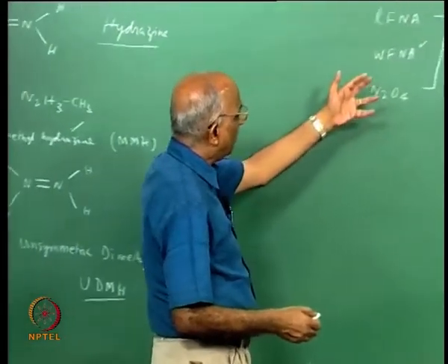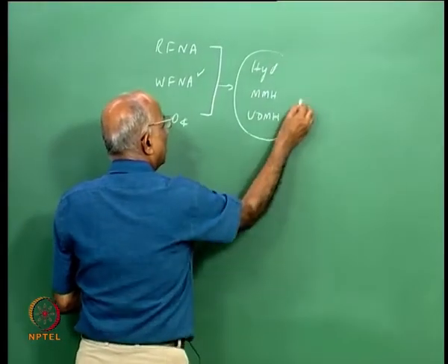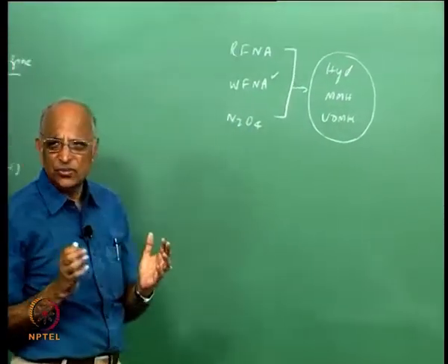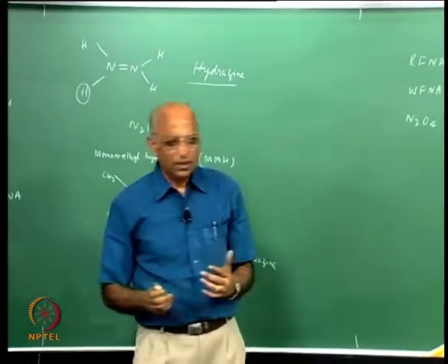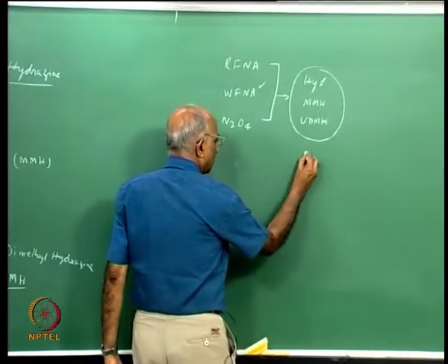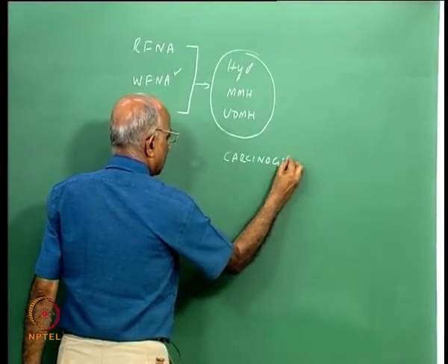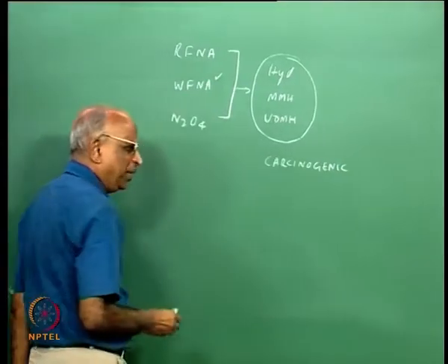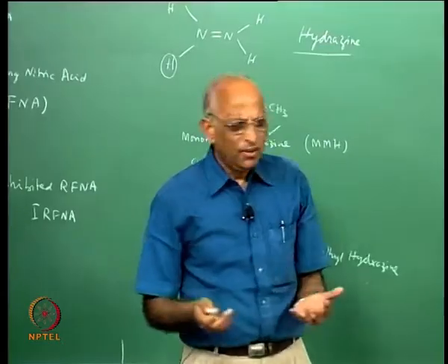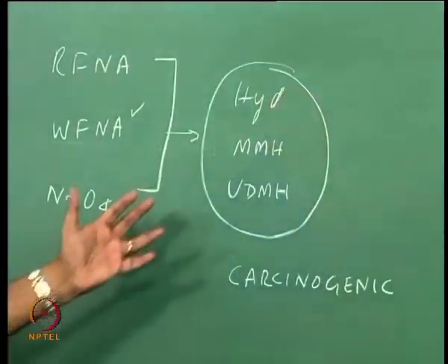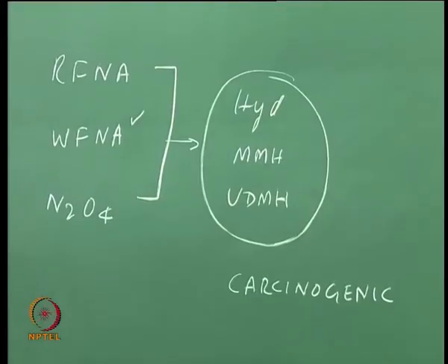All these three propellants, all these three fuels, can cause cancer, and there is a trend in today's world to get back and substitute it by kerosene or something, because we say it is carcinogenic. But being rocketry and using small quantities over a period of launches, we take adequate precaution and still continue to use these fuels. Therefore, now I put the low energy fuels again.